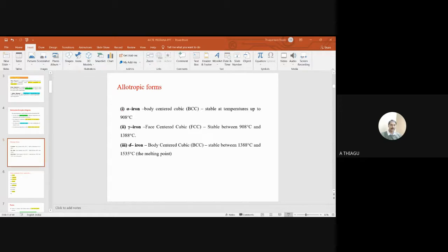So this is ledeburite, one form of structure. Mostly in pig iron, which has a higher percentage of carbon, ledeburite will be formed. It is also a mixture of austenite, gamma, and cementite. The maximum carbon content is 4.3. Previously it was 0.8 only, but in ledeburite it has 4.3 percent of carbon. So mostly ledeburite is formed in pig iron only. One good example of ledeburite structure is pig iron.